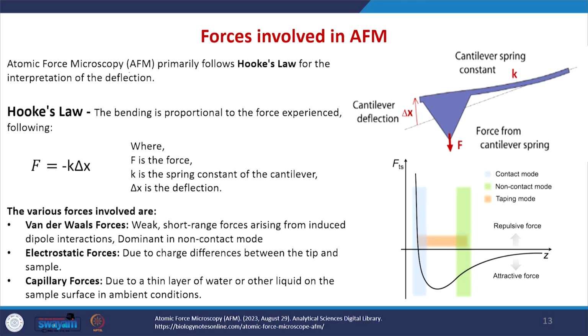Let us see what are the various forces involved in AFM. The AFM primarily follows Hooke's law for the interpretation of the deflection, and Hooke's law is F equals minus K delta x, where delta x is the cantilever deflection and K is the cantilever spring constant. The various forces involved are the van der Waals forces, electrostatic forces and capillary forces. The van der Waals forces are weak short range forces arising from induced dipole interaction, and these are dominant in non-contact mode.